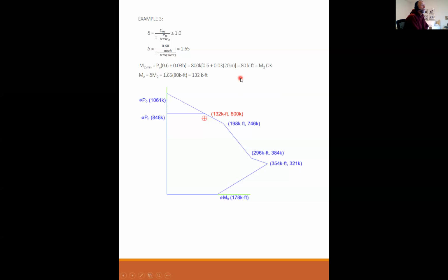I think what they're doing is the Euler's buckling load is very, very dependent upon the stiffness of the member. If you go back and look at how you apply Euler's buckling load to tube steel or flat plate or anything made out of steel, it's pretty precise. But when it comes to concrete, we got this whole problem of cracking.